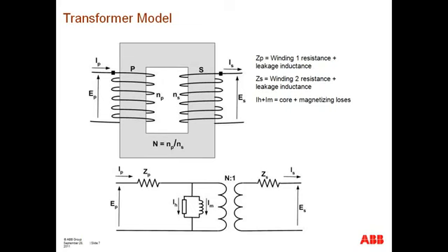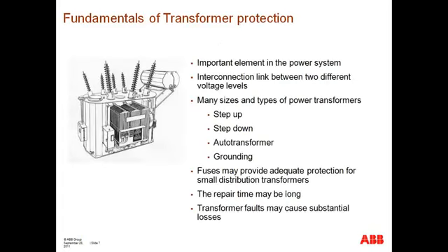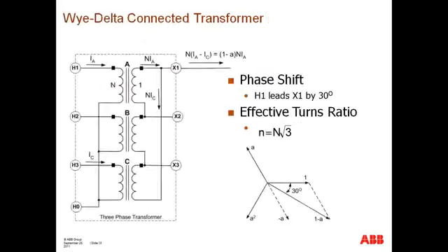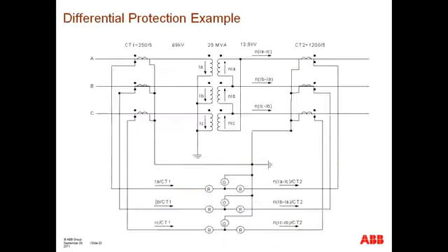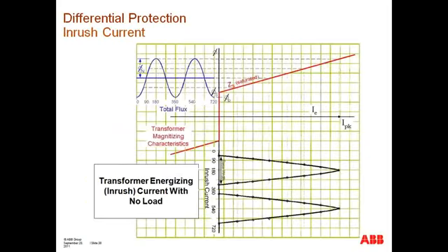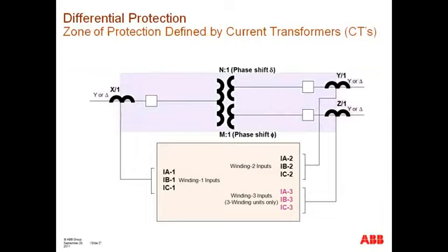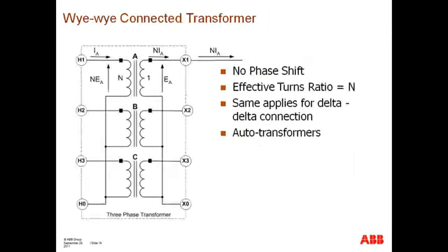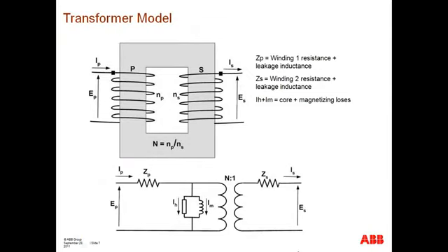So a big part is your source impedance. It's obviously what for the most part is going to regulate that inrush current, along with the point in wave, which again is random. Now, if the question is more in regards to the amount of second harmonic content, that is really something that the manufacturer of the transformer needs to provide, because that's primarily a function of the material and the type of construction that was utilized on the core, which in turn is the primary parameter that affects how this branch behaves.